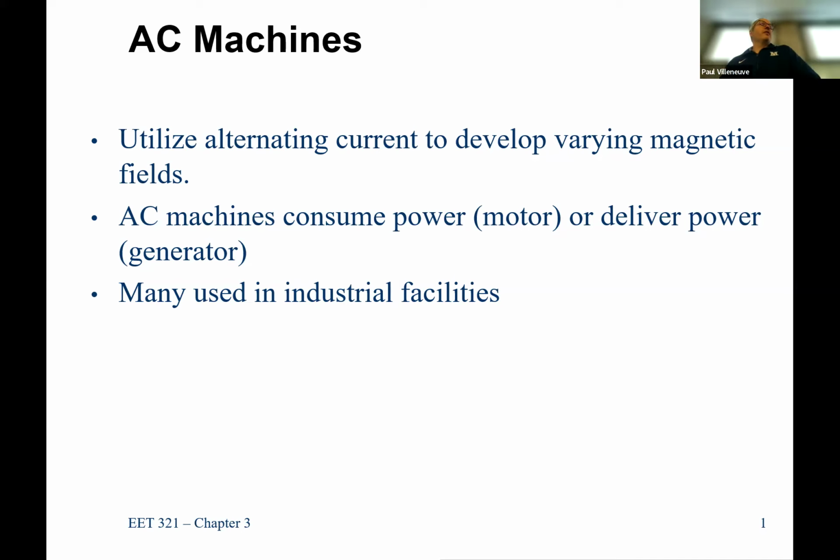Like electric vehicles or hybrid vehicles, one of the advantages of using a hybrid vehicle is the brake system, the regenerative braking, a term most of you have probably heard. That's where a hybrid really gets the big bang for its buck. When you apply your brake, unless you stomp on it, you hardly use your brake pads at all. You're relying on regenerative braking to take energy out of the wheels and reduce the momentum of the car, and you're pulling that energy out and sending it back to a battery pack. That's the regenerating brake component.